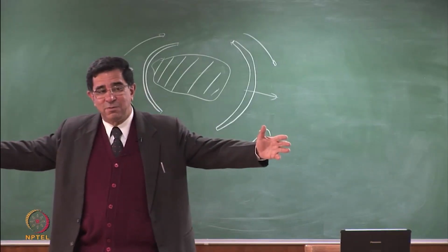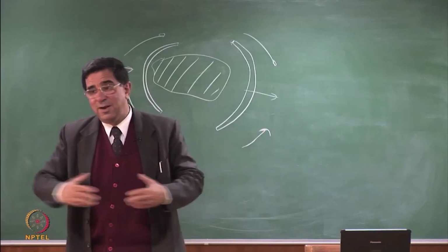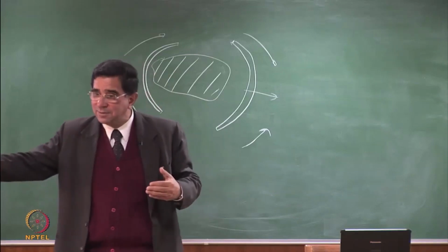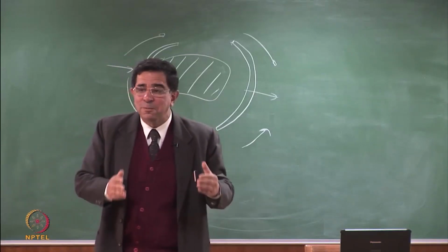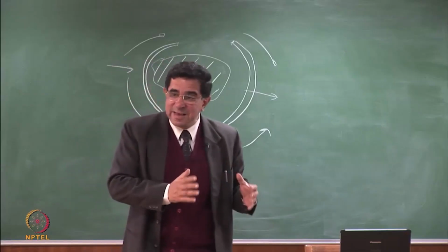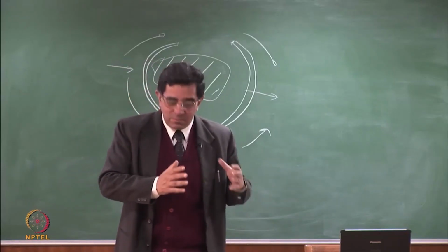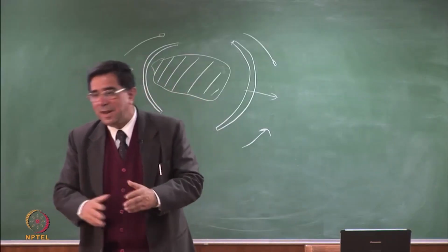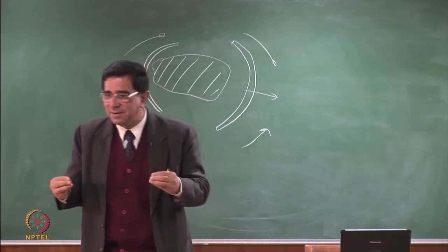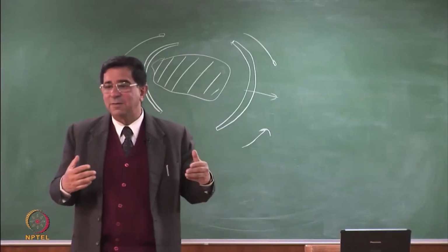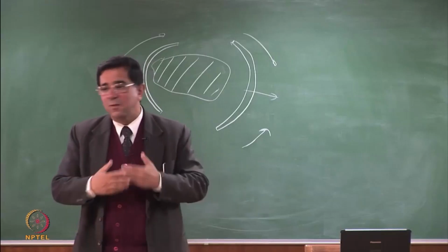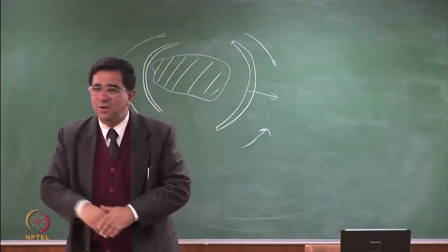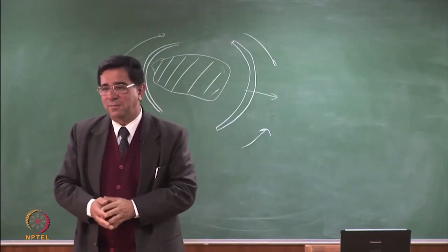And once they made this huge landfill bases, now you start filling it up. And it is absolutely wrong to fill it up in horizontal direction. You are supposed to make small phases and finish the phase to the full height and then cover it and then go to the next. That is the only way you can get less leachate, and that is the only way you can prevent a lot of infiltration into old waste. If you spread it out, even if you are doing it over 5 years, you are getting 5 monsoons falling on your waste, you did not operate a landfill well.